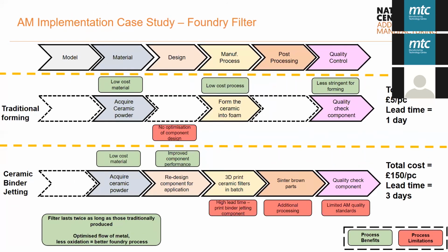Okay. And we've got the orthopedic implant manufactured through powder bed fusion. I think the question is, did it require heat treatment to remove residual stresses on the part? Yeah, for laser powder bed, it might do. It depends on how your part is orientated.